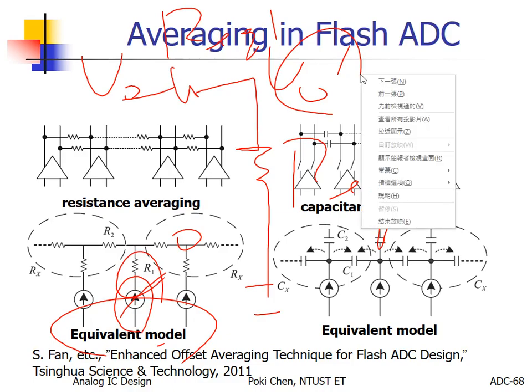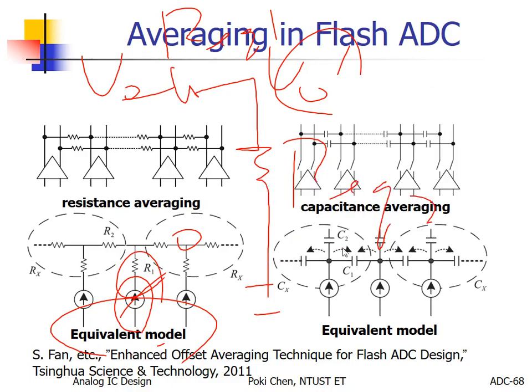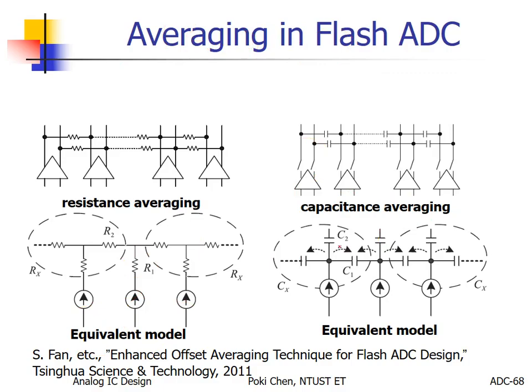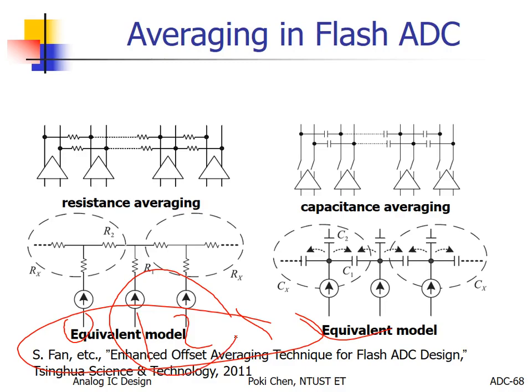And if you are lucky, no, if you pay attention to your layout pattern, 0, 1, 2, 3, and you try to randomize the output of your current sources, your voltage sources, then congratulations, they are uncorrelated after fabrication.